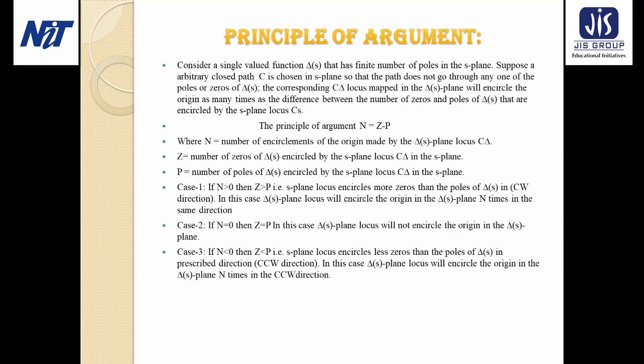And the next one is the principle of argument, that is Cauchy's principle of argument. Here we are considering that delta s is a single valued function, and single valued function means for each point in the S plane there exists only one point in the corresponding delta s plane, which is a plot of the imaginary part of delta s on the y-axis and the real part of delta s on the x-axis.